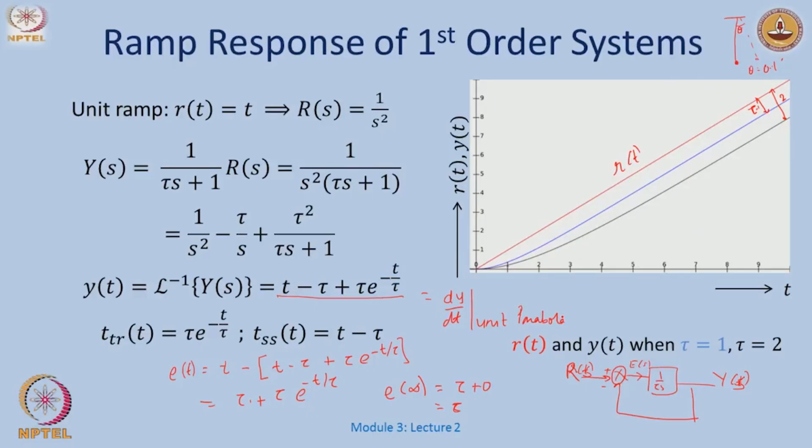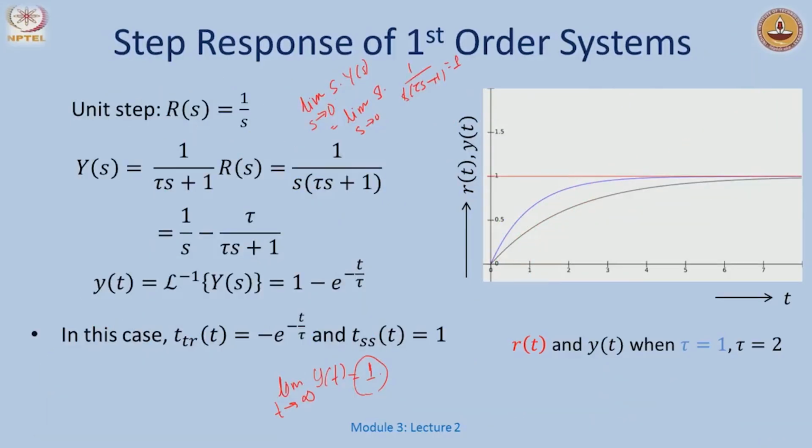So, I differentiate the response, I get now the response to a unit ramp. So, the differentiation holds until now. Now, let me differentiate this again, dy by dt when the input is a ramp. This will be 1, this will go to 0, this will be a minus e power minus t over tau. Just see how this looks: 1 minus e power minus t over tau. We will go back to the slides, and this is the same, right, this one.